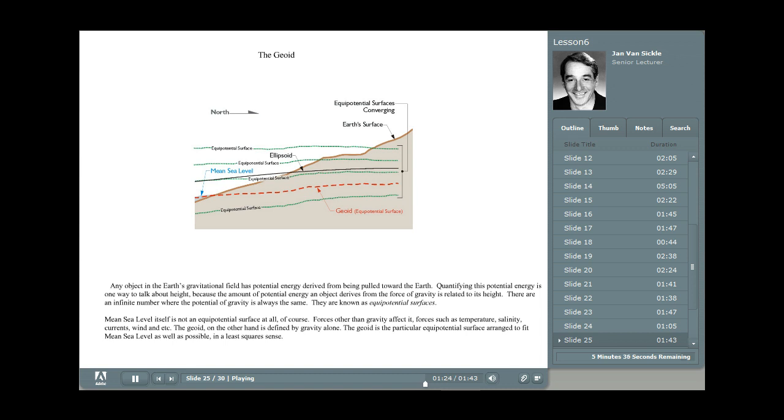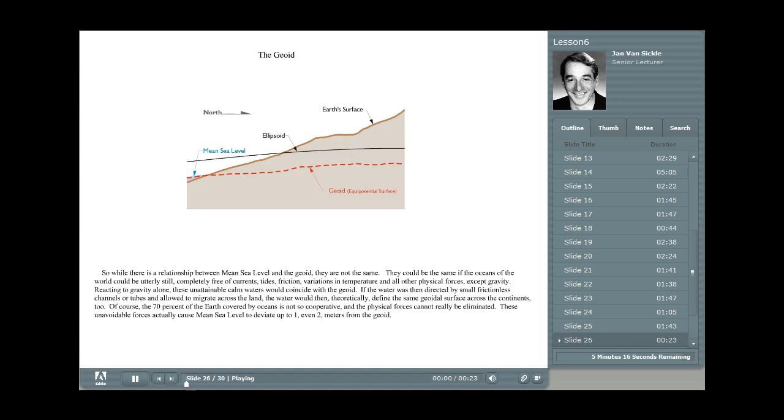And as you see in this image, the geoid and the ellipsoid are not the same. Now, of course, remember that the legacy heights determined by optical instruments in the past were always relative to the geoid, because, of course, the instruments were oriented to gravity. However, GPS heights are related directly, at least, to the ellipsoid, two different surfaces.